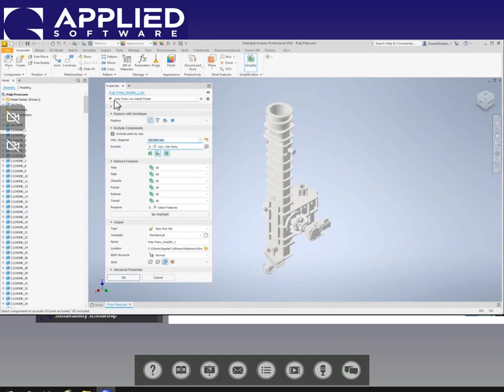But first thing I want to do is review one of the presets I already have here. I have a low detail preset. So what that means is I'm trying to strip out as much content from this thing as I can to make it as simple as I can to share with Plant 3D. Because Plant 3D, especially if you're going to use multiple instances of this thing, is really going to need to have this file be as small as possible.